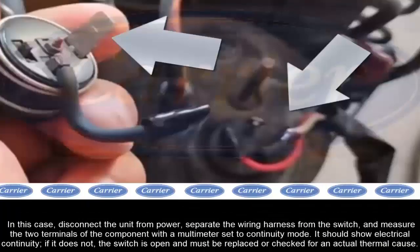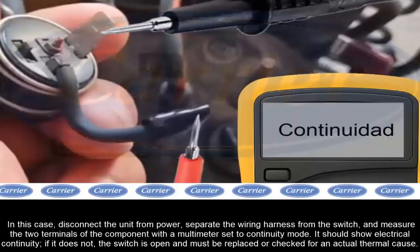In this case, disconnect the unit from the power supply, separate the switch's wire harness, and measure, with the multimeter on the continuity scale, the two terminals of the component. It should show electrical continuity. If it does not, the switch is open due to an internal failure or activated by an excessive temperature.